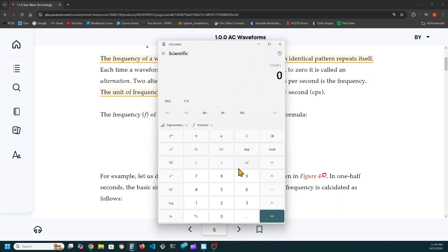Over in Europe, they use 50 hertz. So we can reciprocate that, and we can find that their waveform, 1 cycle takes 20 thousandths of a second or 20 milliseconds to complete 1 cycle. Okay. Ours is a little bit quicker because we use 60 cycles per second instead of 50 cycles per second. So theirs is 20, ours is 16 milliseconds, 16.7 milliseconds.